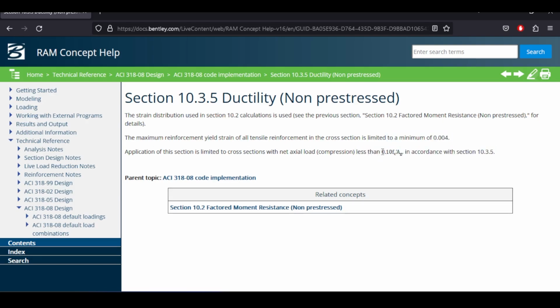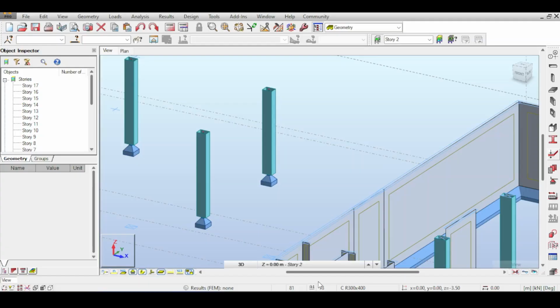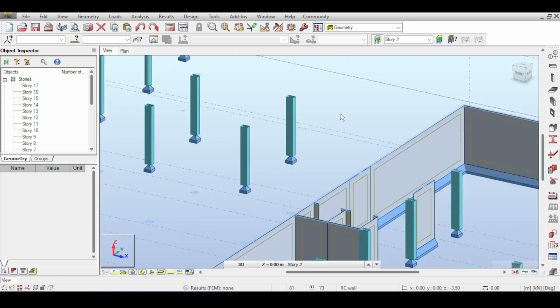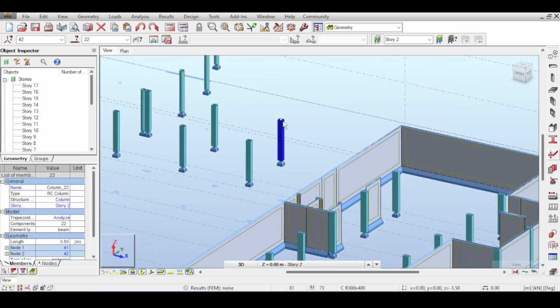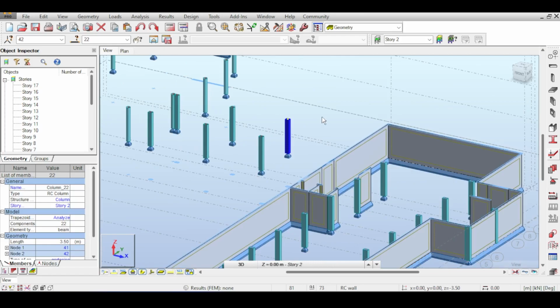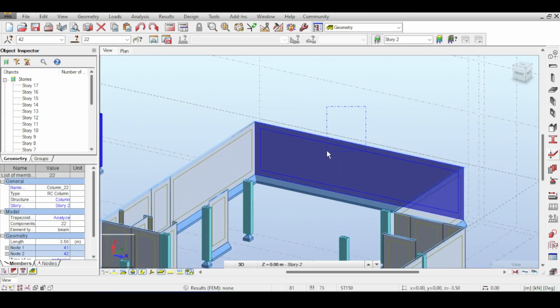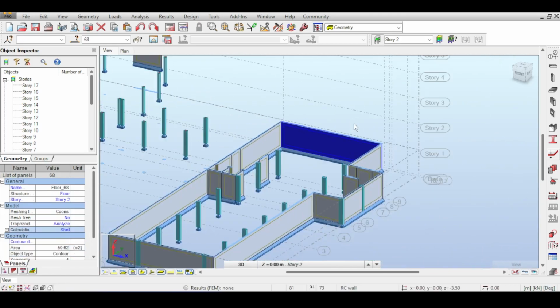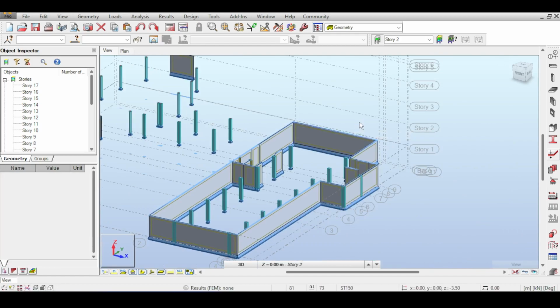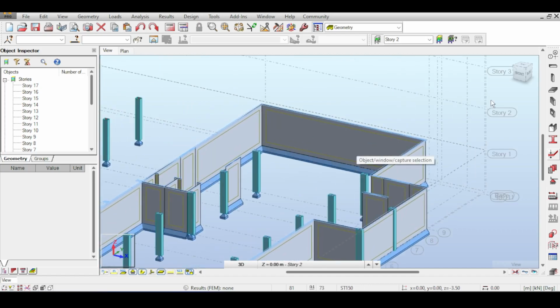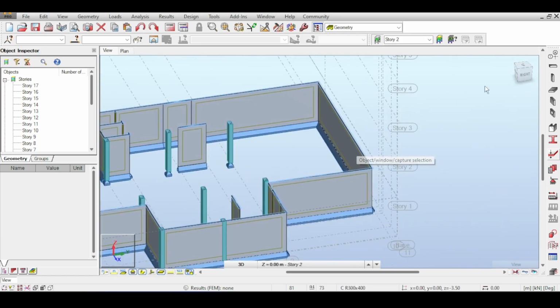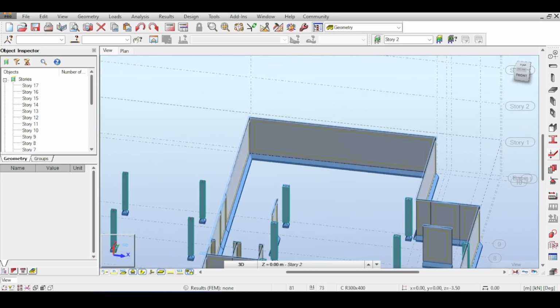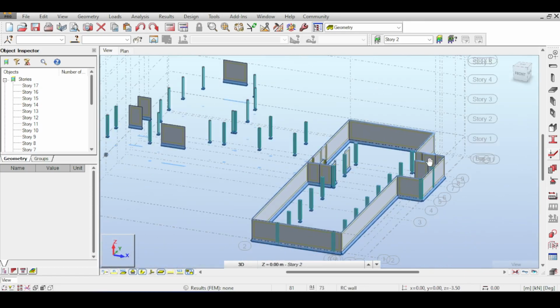Now, I am using this equation in my mind, this is what I usually use, to try to differentiate between what a beam is and what a column is. Now, of course, those columns are going to obviously be axially dominated, but I'm thinking about the basement walls here. Should I apply 0.35 to them or should I apply 0.7 to them? And the reason why I'm not sure is because I don't know how severe the earth pressure is going to be on the basement wall in comparison to the axial load being carried by the basement wall. So I am kind of undecided yet.